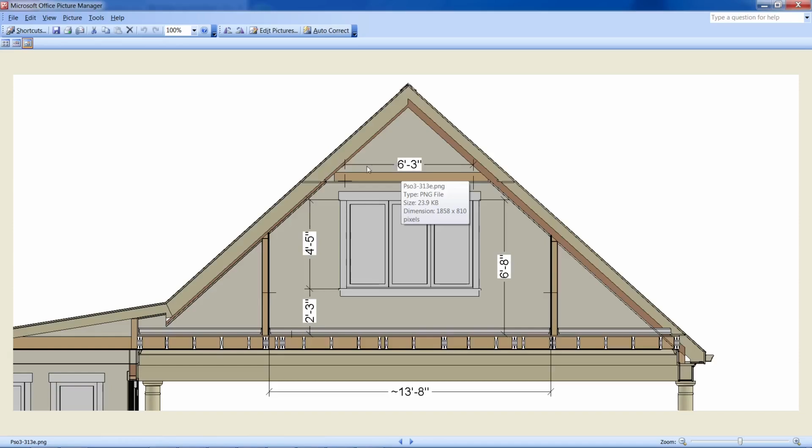As you said, if I have any ideas, feel free to let you know. But now you had talked about, I think you intended trusses, but if this were conventionally framed with some arrangement like this, with these floor joists running out west and then some sort of beam across here holding those, these floor joists could actually be cantilevered and you could actually have a balcony out there, or that could cantilever out and be additional covered space.